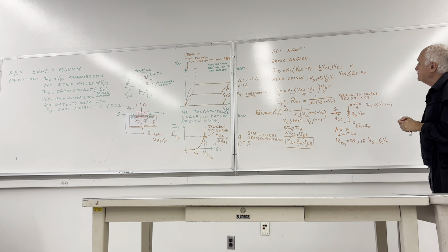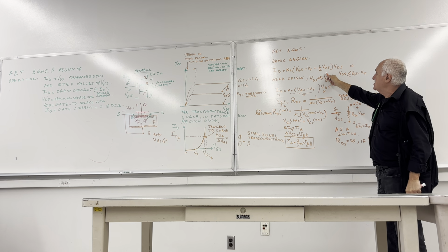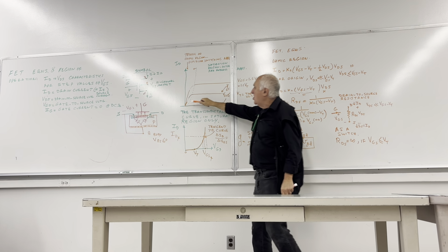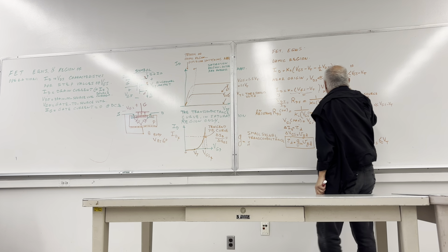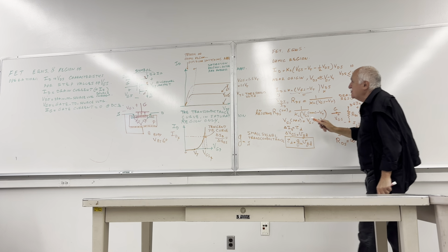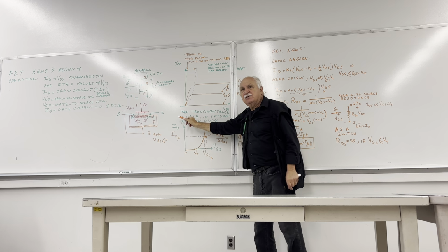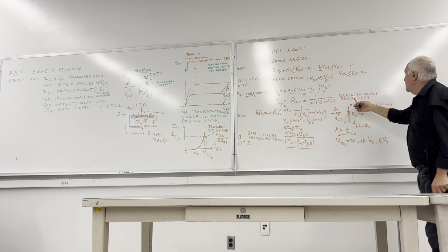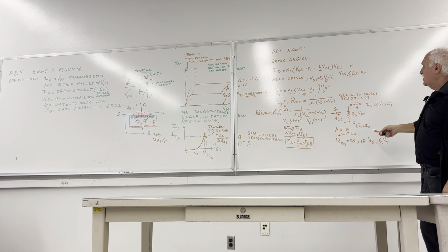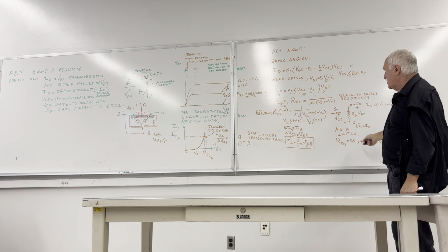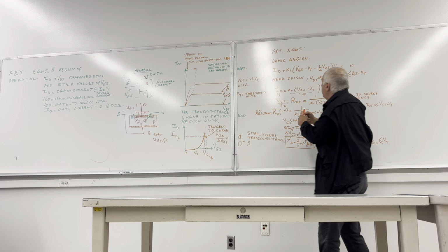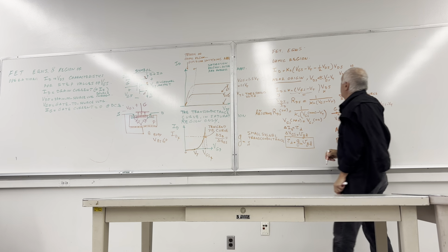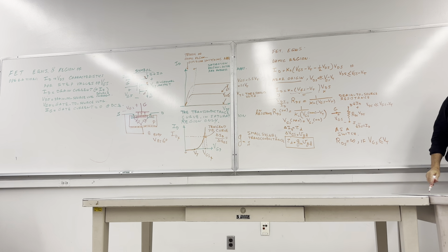So next one, this was the exact equation which explains all of the ohmic region, all the way to here. And this one is specifically only for the origin. Here I wrote that drain to source resistance is equal to that small signal resistance near the origin. That condition applies near the origin, as an on and off switch.